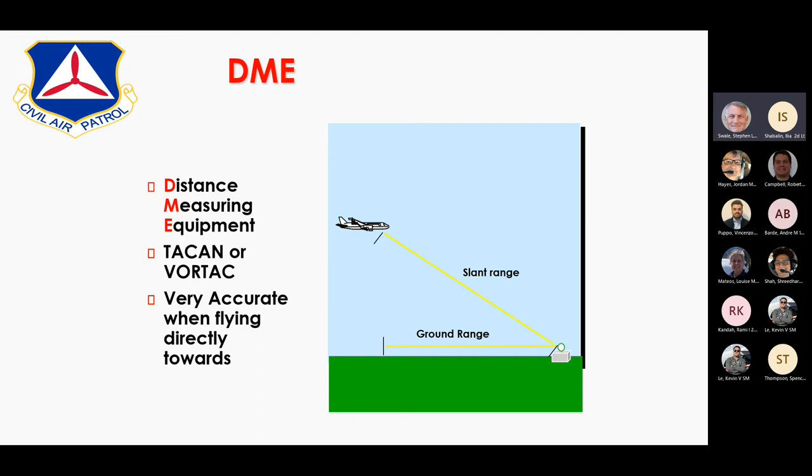Let's say that it's 1 mile away from the transmitter there, and you can see that part of the ranging, it'll tell you that you're 1.4 miles from the transmitter, when actually on the ground you're horizontally only a mile away. With GPS, this slant range error is not present. It's simply a horizontal measurement from the location of the DME transmitter to the aircraft horizontal position.